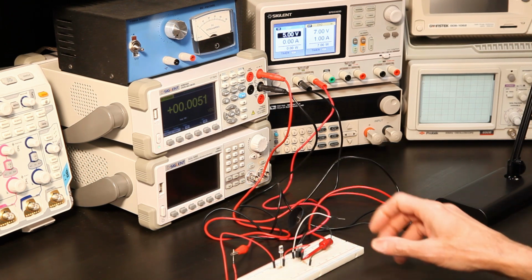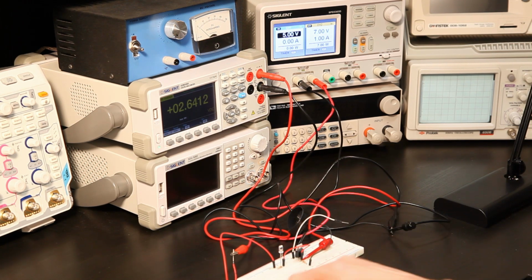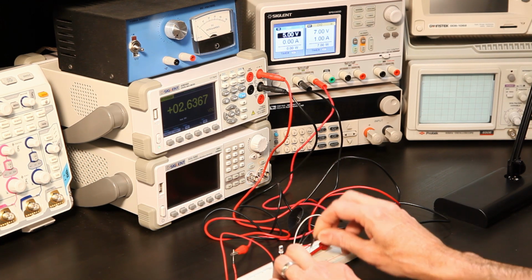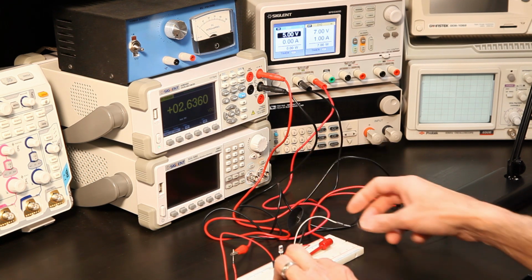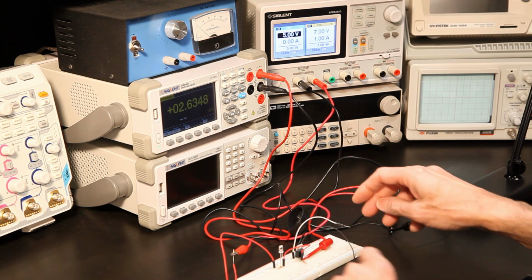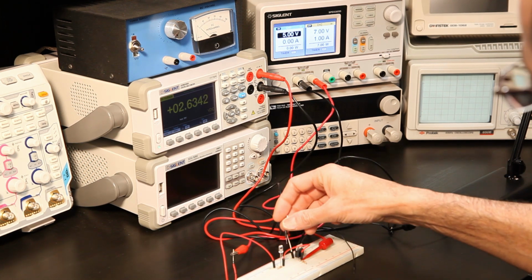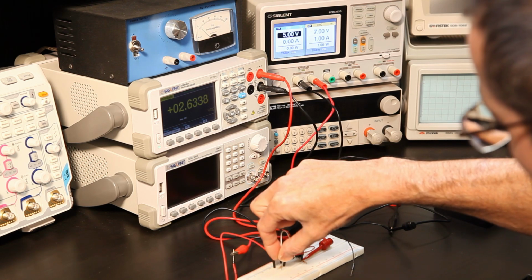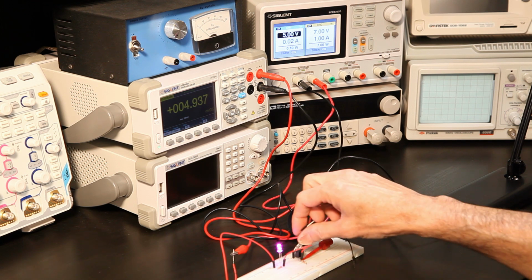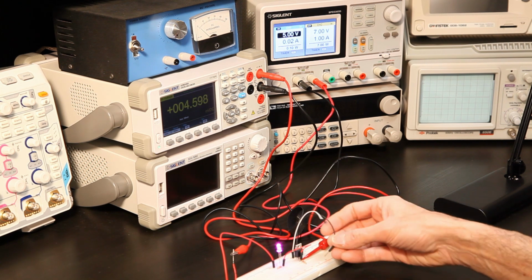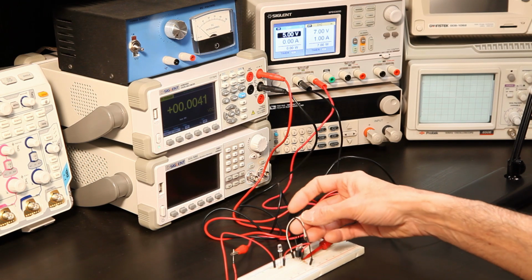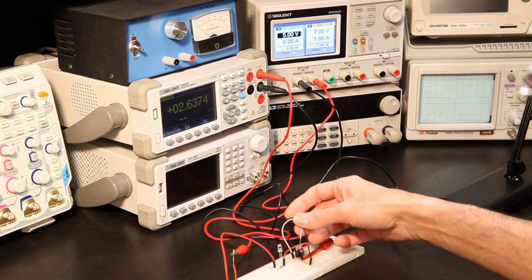All right. Now I want to show you another interesting phenomenon that you need to pay attention to if you're using a MOSFET as a switch. You'll notice that I've got a pull-down resistor here. And if I remove that pull-down resistor, which I just did, and then switch the MOSFET on, it'll stay on. It won't go off. It's kind of acting like an SCR. And so for a lot of these MOSFETs, you're going to want to use a pull-down resistor if you want it to turn off when the gate voltage is removed.